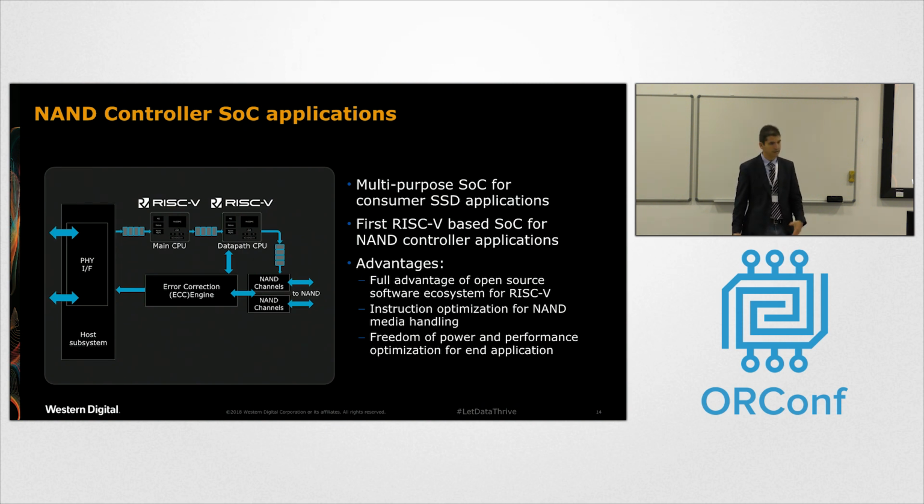Then there is an internal link to what's called the south end. The south end contains another subsystem that is talking to the NAND channels, meaning it's taking one host block I/O and usually breaking it with some reasonable scheme, like 4K into 8 times 512, and it's talking to the NAND channels and using an error correction code engine. So when it writes, it appends ECC.